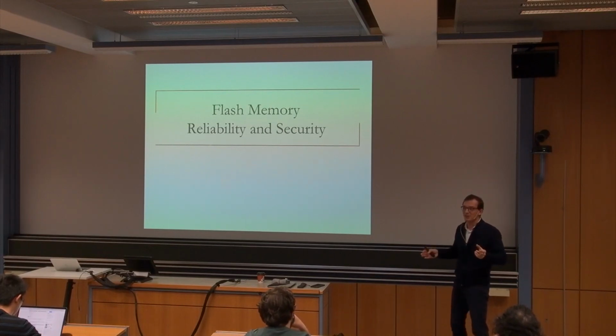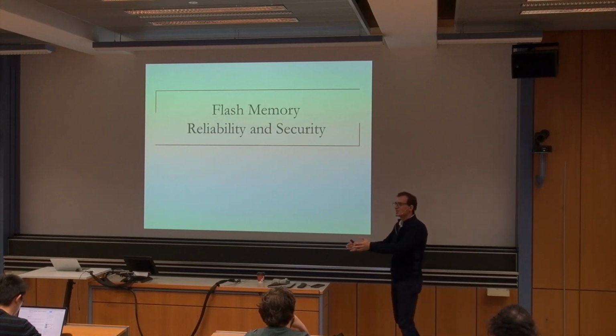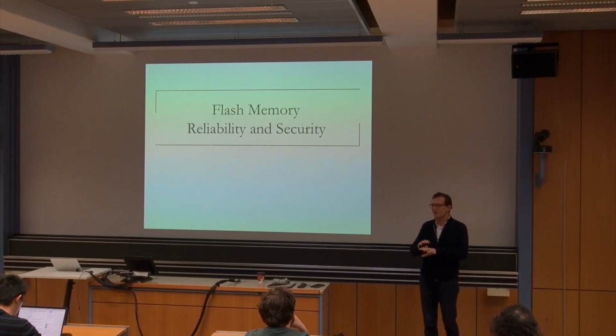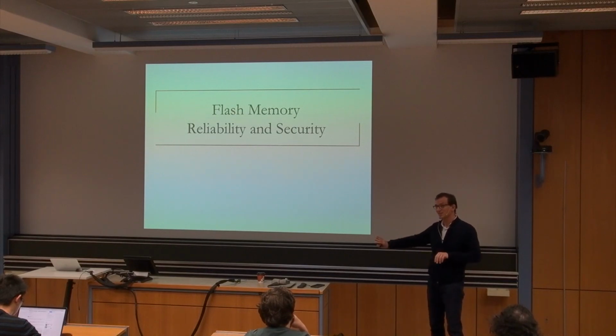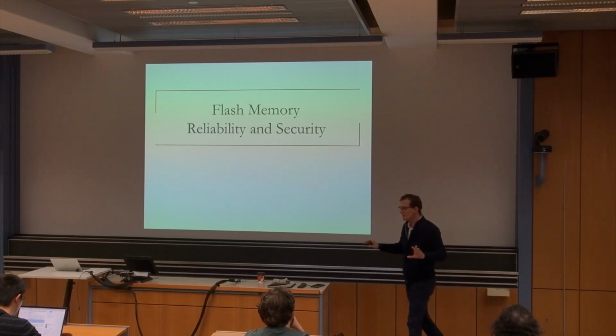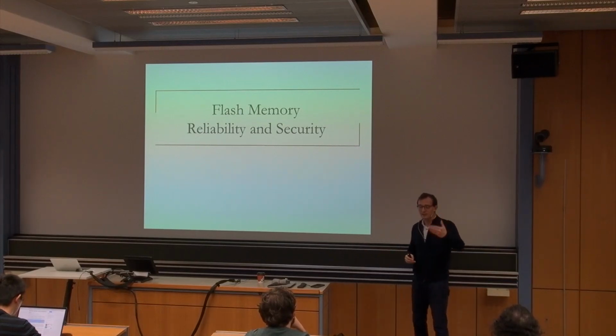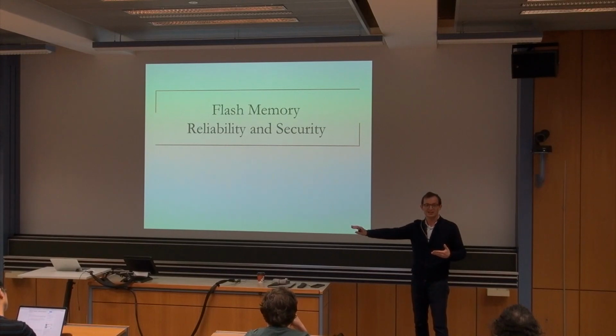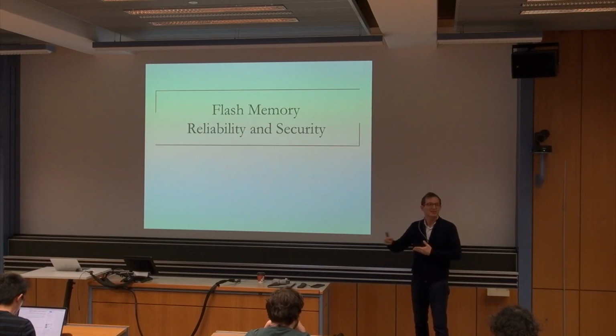Well, what you do is actually have blocks that are writable at that moment. So you have a set of blocks. Some of them are erased. Some of them are currently being written. And some of them are valid, meaning you already have valid data inside them. And the flash translation layer needs to keep track of them. If you want to read a page and write to it, what you do is you read the page, modify the value, and write it to some other block that you're currently writing to. Which means that you actually remap the page, right? You remap the page from this location to this location.